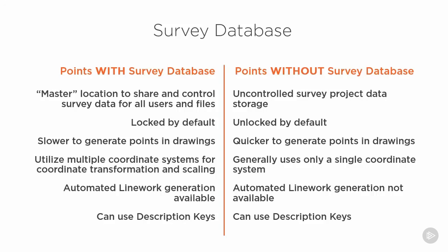If we were to have to create the database and then import the points into the database, that takes a couple of extra steps. So with the survey database, we can also utilize multiple coordinate systems, and we can do coordinate transformation and scaling of points where we can't really do that without the survey database. They're really only going to use the currently set coordinate system, no transformation really when you import them. And the very, very important thing is the line work generation. You're not able to do that without the survey database.